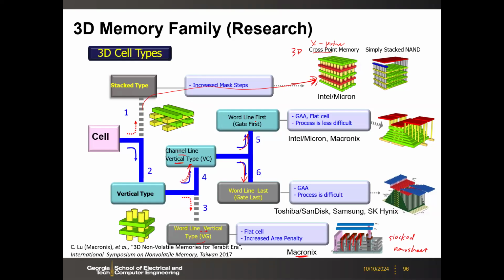It's gate first. But then when you switch to the high-k metal gate in the logic transistor, it is a replacement gate, the gate last. You have some poly gate as a dummy, and then you use that to form your source and drain. And after that, you remove the dummy gate, that is like a sacrificial layer, and then you redeposit your high-k metal gates.